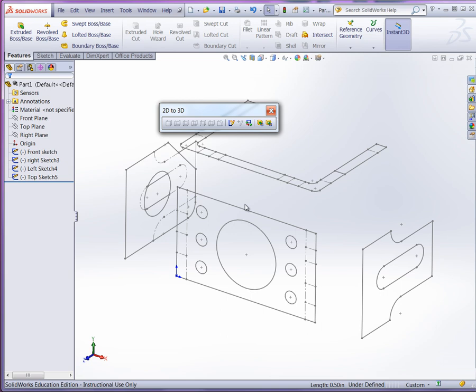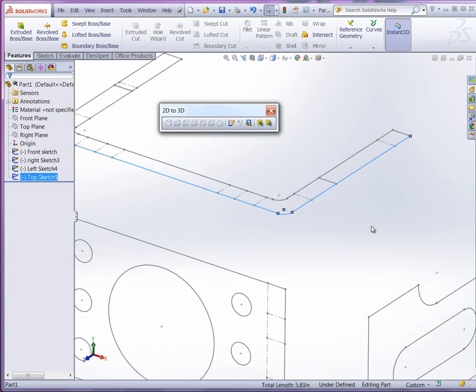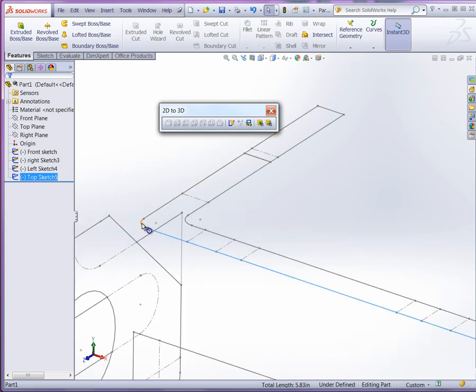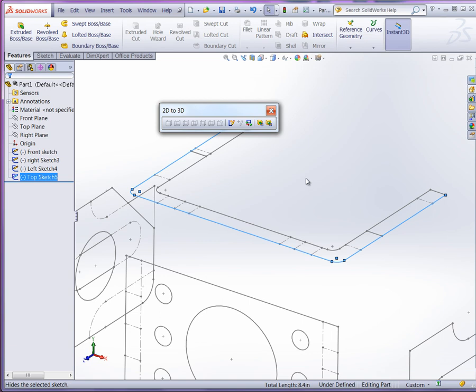But now what you want to look at is what are going to be the regions or the single edge that I can use to create the base profile. And I would suggest you have many different options. So for example, here's what we could do. If I started with, let's say, using Control and simply selecting the outside edge here, just using that outside edge here, and then you'll notice I have the option to convert to extrusion.